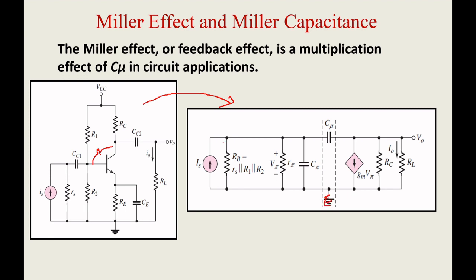Okay, so then you have your r pi, that is a forward bias resistor, and forward bias capacitor, and this is the reverse bias capacitance. The reverse bias resistance is open circuited, right? So here you want to be very clear, I used a simplified model.